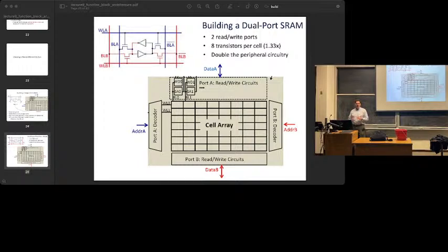For an FPGA, the main cost of making your physical RAMs have more ports is area. They just get bigger and bigger. Now, if you needed highly ported memories all the time, then you should just do it. Because we also saw, when a person asks for lots of ports and you only have, we did it with 2 ports last week, it's pretty painful, right? It's pretty painful to give the user more ports when your physical RAM doesn't have many. So if you need a lot of ports, then probably you should build highly multi-ported RAMs. But if you don't usually need that many, it's definitely not free. Does that make sense?